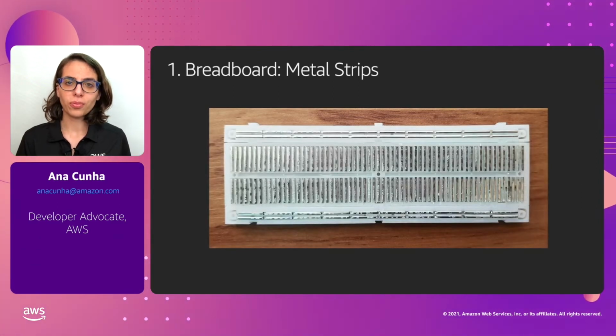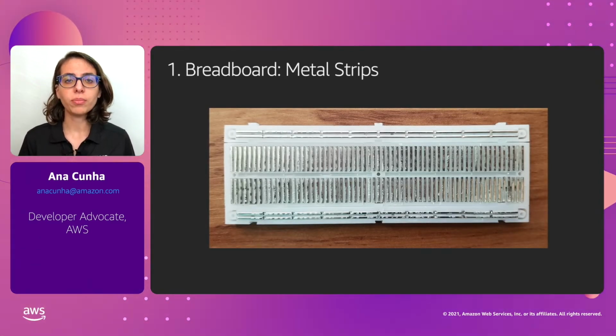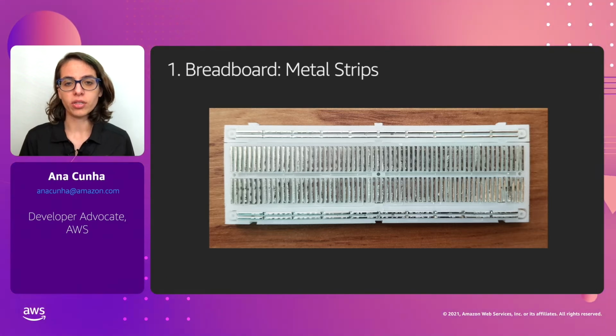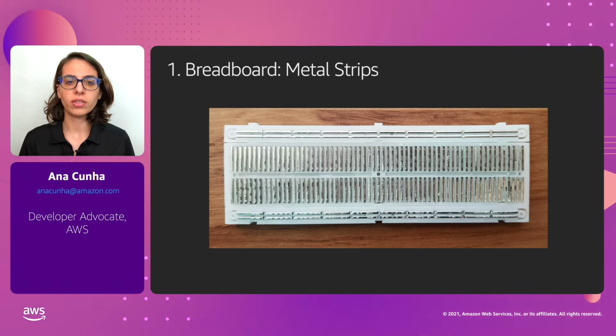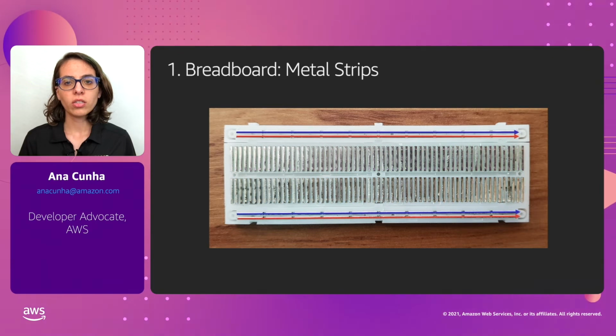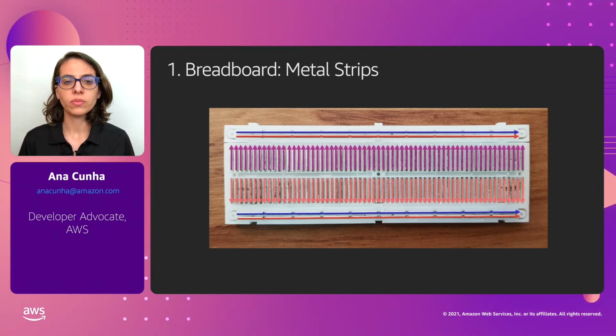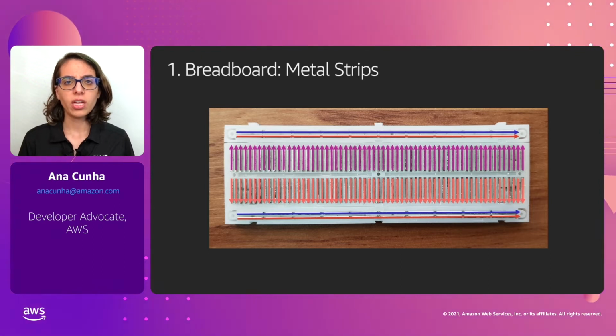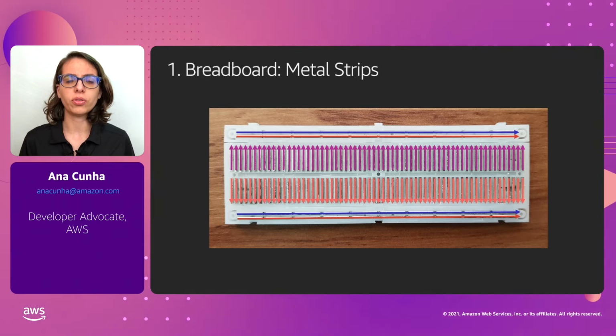The back of the breadboard is usually closed, but I opened mine up so you could take a look. This is what the metal strips inside the breadboard look like. They are the ones responsible for connecting all the pins. These are the metal strips connecting the pins on the terminal strips and on the bus strips. We just have to keep in mind how breadboards work and how the pins are connected so we can safely use them to build our circuits.